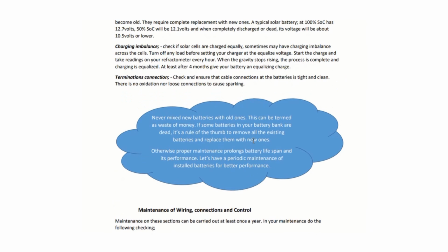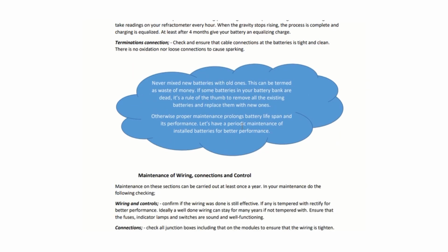The last one is checking the termination connection. Check and ensure that the cable connection at the battery is tight and clean. There should be no oxidation and no loose connection to cause sparking, because if you don't do that, things may heat up. And it's a rule of thumb that you should never mix new batteries with old ones. This can be termed as a waste of money.